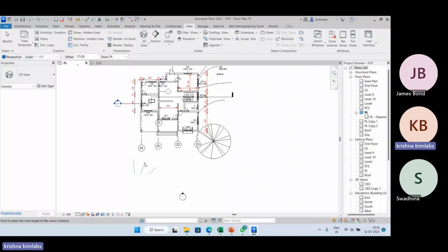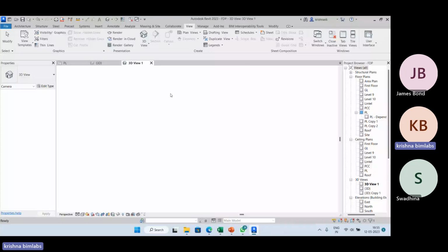Here you can see in the ribbon area, it is from plinth. And you can see the offset also. Offset means the height of the camera, from plinth, it will normally be a human's height. So the camera is 175 centimeters above the plinth. That is the offset. Then take different pics.